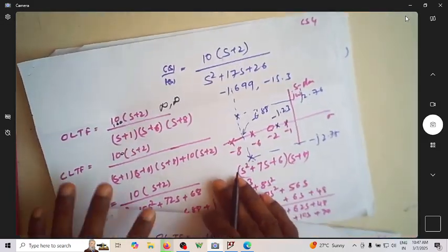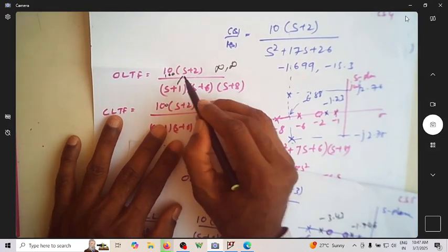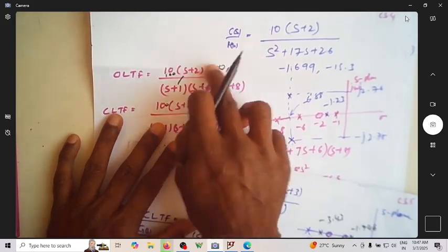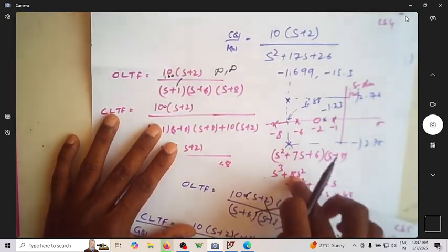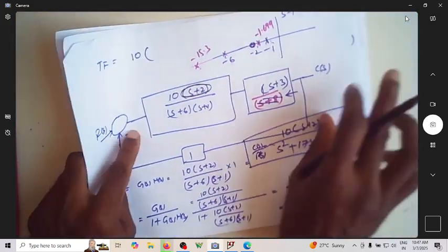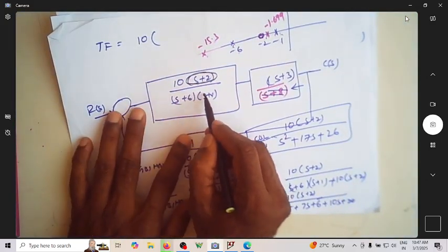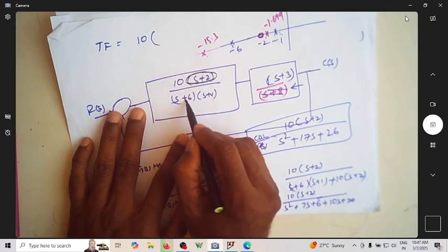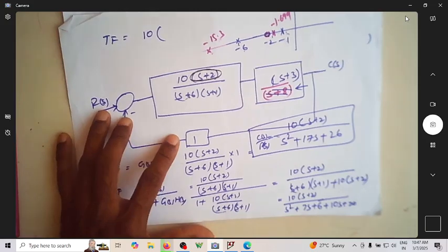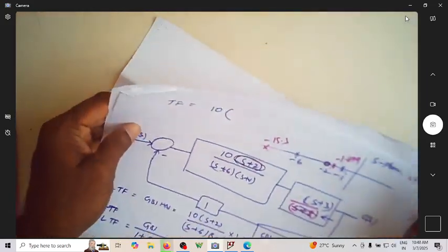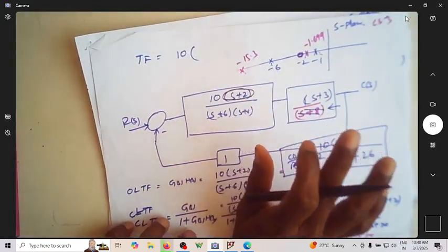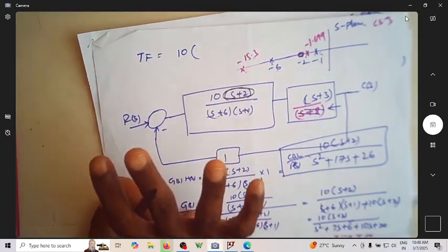Whereas in these two cases, you had this pair. Where is the pair of this? Its pair is sitting at infinity. That's why they are going in search of that. How about this case? So this has got its pair. Where is its pair? Its pair is at infinity. That's why it keeps moving. So in control system, poles and zeros always come in pairs.